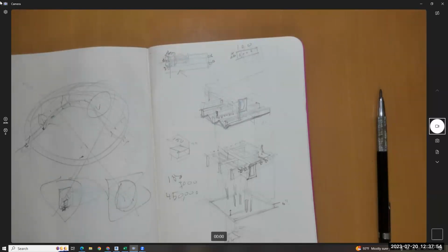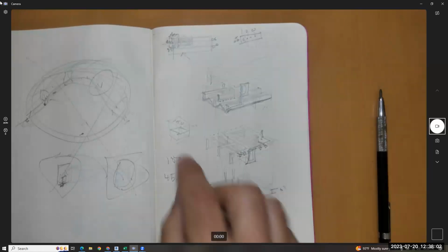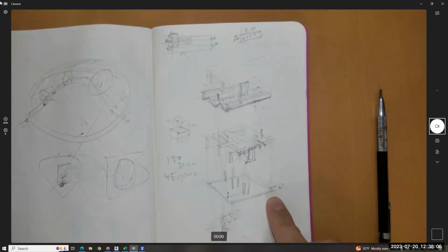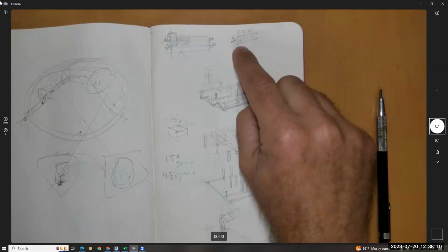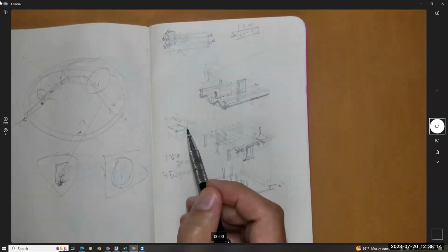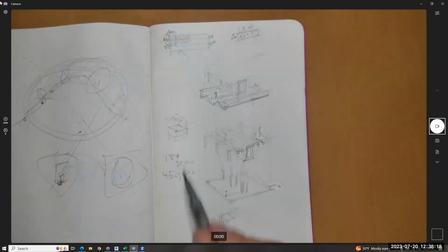You just have to think through it. This is what I want to get you to. It really is just visualizing these things. If you know it's 150 pounds per cubic foot, even if it was a 4-inch slab, it's 3 4-inch slabs per cubic foot. I could divide that by 3, and then it would just be 2 times that, right?